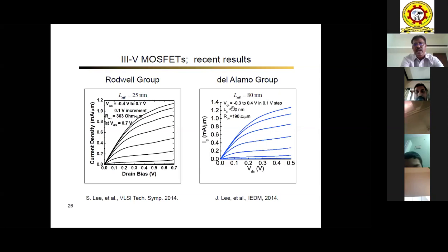First, make sure that your device functions at the long channel platform, and then you move to the short channel platform, and then see that the short channel effects are not that predominant in our design. Not necessarily all the short channel effects, maybe some of them, by trade off with some other parameters. That is the idea of the current researcher at the moment.